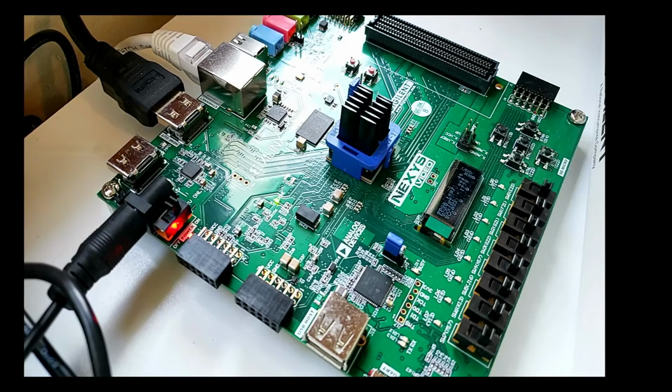HDMI, USB, UART, Ethernet, the LEDs and the switches and whatnot. The chip is programmable. The board has pretty fixed traces here. And so consequently, if I want to access my switches and my LEDs, as well as my clock and my reset, as well as anything on this board, I can call a signal named switch in my design and named LED in my design, but I have to constrain where that signal is actually going to correspond to on my chip, because ultimately, you can't really visually inspect it and see if that's the case.